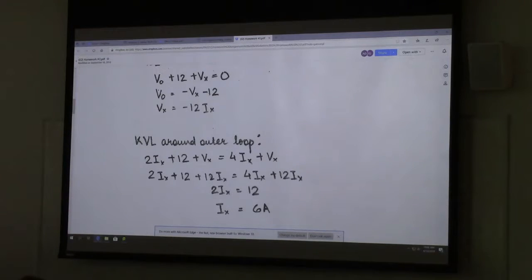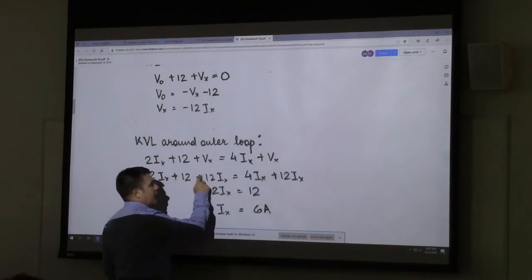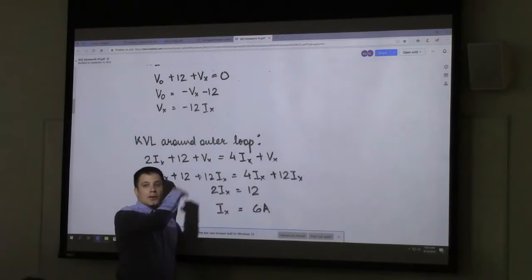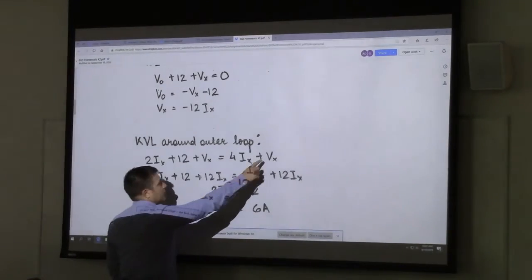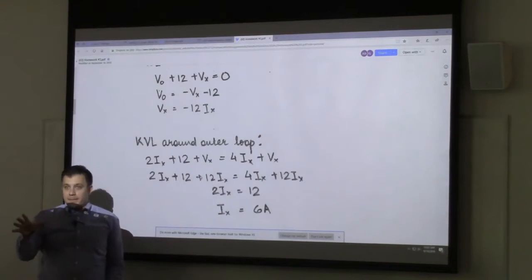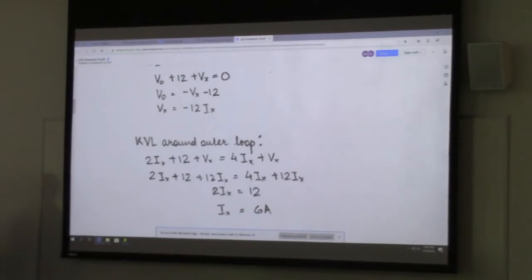I think what ended up happening was that, like you said, because they cancel out anyway, the Vx and the Vx, this is a mistake. They use negative when it should be positive. The values go away anyway. So what ended up happening was they got the correct answer even though they used positive 12 Ix instead of negative 12 Ix. You see what I'm saying? If this were positive and positive, or this were negative and negative, as she just pointed out, they still go away, which actually we should have noticed up here that they would go away regardless. Anyway, this should be negative 12 Ix.